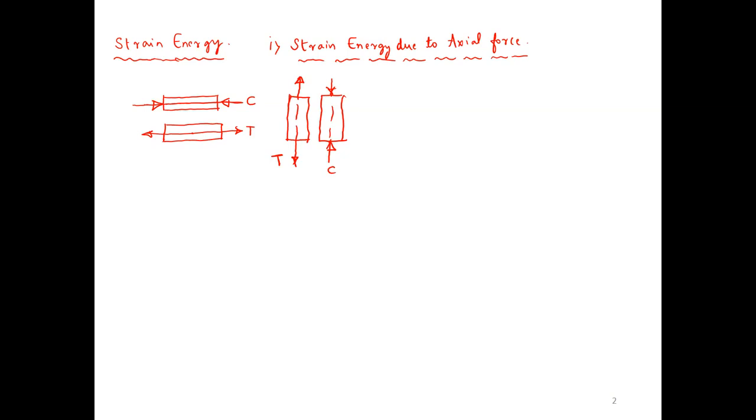So only these kinds of forces are expected. My question is a direct question. Only axial type of force, in which type of structures can we expect it? The options are beams, frames, columns, trusses. Trusses. Why? Because there is no shear force.